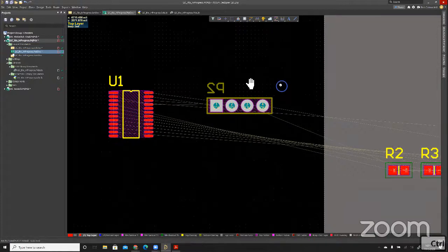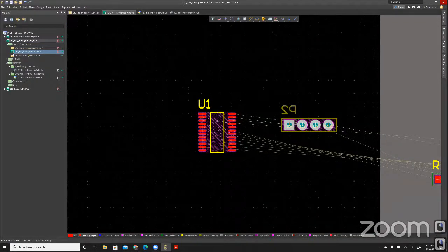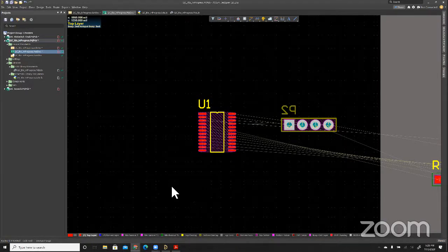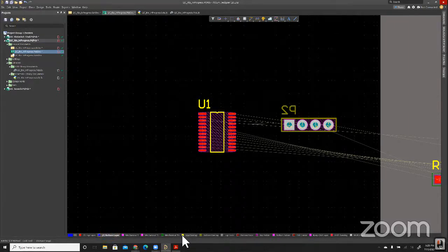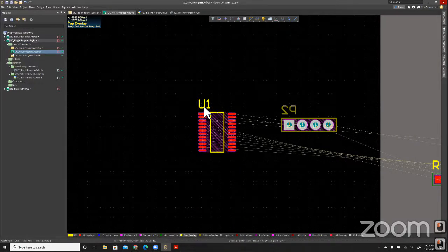So in a PCB doc or in the PCB library footprint stuff, you get these other things down here. These are the different layers. For some people, this may make intuitive sense. Your PCB is pretty much several sandwiches stacked together of copper. And so your top layer is a layer of copper, your bottom layer is a layer of copper. And then there's some other things in here too. So top overlay is typically the white text that you would see on top of the board. It doesn't electrically do anything. It's just informative for the user.